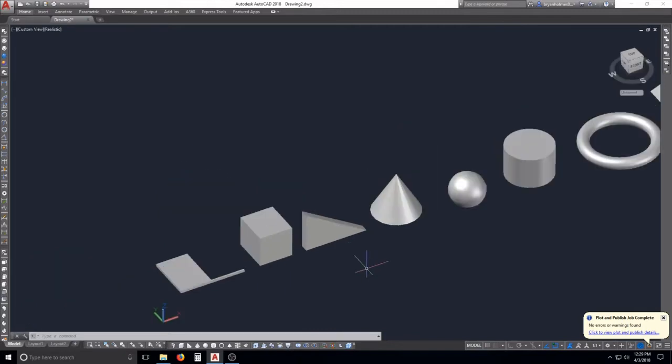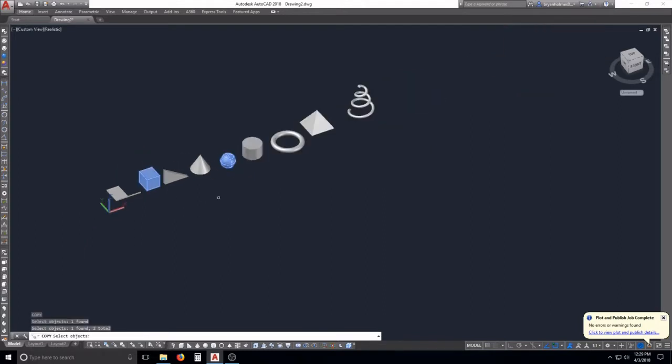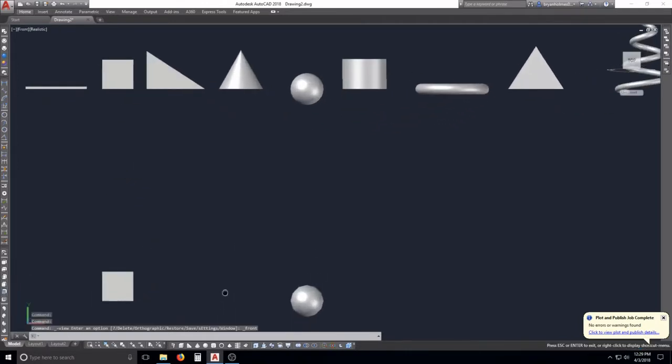And for instance, what I'll do is copy these guys down. So it's CO in my case for copy. That's what I have my alias set up to. Enter. We're going to copy this guy. Let's just copy him down. And enter, and then drag. Let's turn my ortho on, F8. Turn that down. And now we're going to look at it head on, or front view. So now we've got a straight front view.